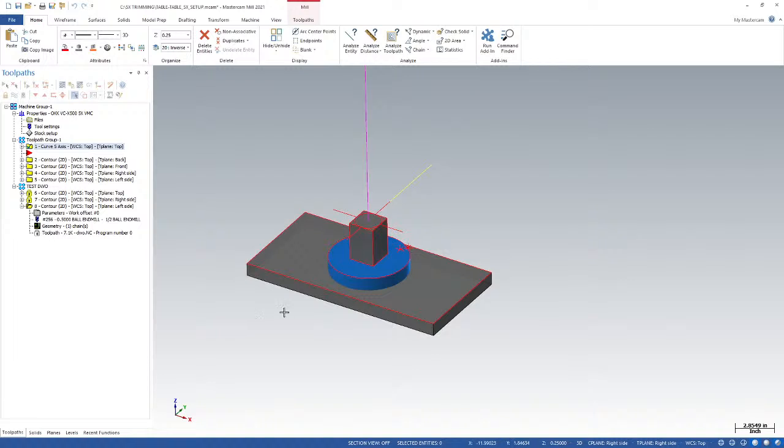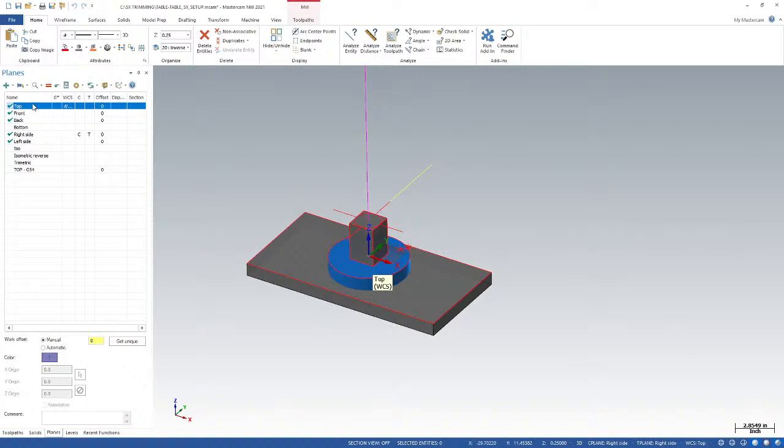In Mastercam, all of the tool plane based tool paths start out as a planar cut. And so whether we're machining in an orientation that matches our WCS, so for example, our WCS for this op is top. So if I machine in the top tool and construction plane, we're machining with the rotaries at 0.